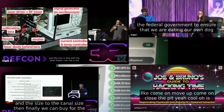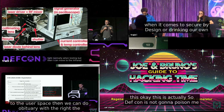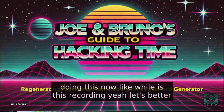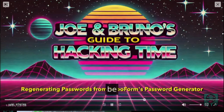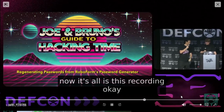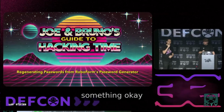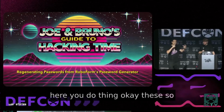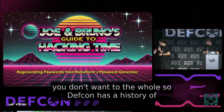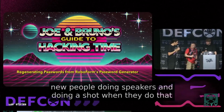The flexure just lets us direct the light up and down very easily. A shutter is to really tighten our beam. So even though we're collimating this laser beam, we want to get a really tight beam, and a shutter just lets us close that even further. And behind the lens, there's a laser diode. All of these you can buy separately. And the nice thing is that with the laser diode, I can use a red light normally when testing, but then I can move to the infrared where we don't see it. So these are the actual components I'm using. The obligatory turn on the fog and check out the cool red laser beam.